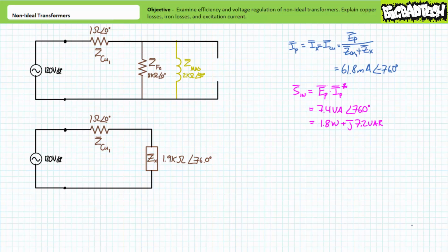However, a small amount of real power is continuously being dissipated in the resistor accounting for iron losses associated with eddy currents, and a very tiny, almost negligible amount of power would be dissipated in the resistor accounting for the internal resistance of the primary windings. In summary, non-ideal transformers performing absolutely no measurable amount of real output always consume a relatively constant amount of reactive power and a small but measurable amount of real power.